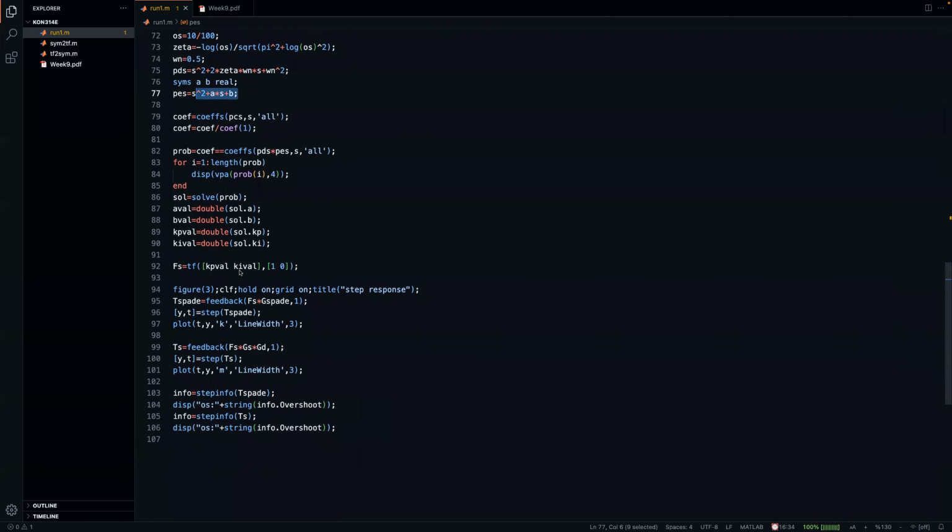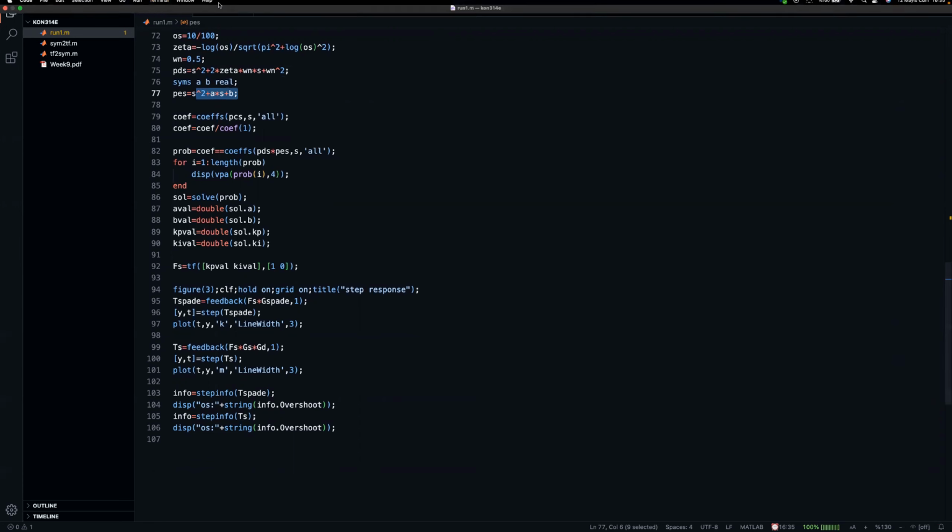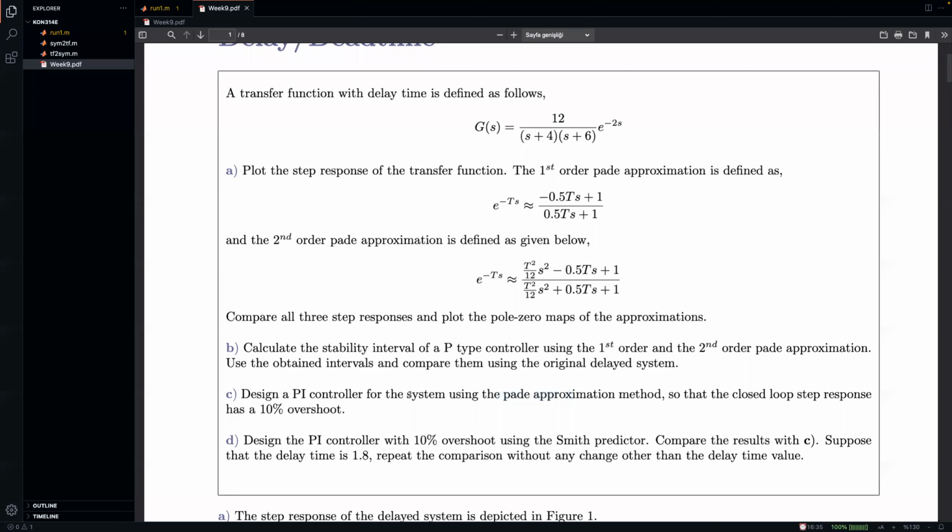And then you have to, of course, again, use tabulation and come up with the best solution that you can and design that. But I'm going to skip that part because I am going to introduce you to these concepts. And my aim here is to give you a basic understanding. And from that on, you can just try your best or design it yourself. So up to this point, we've seen that there's something called the Padé approximation, which takes out the nonlinear term, plugs in the Padé approximation, and from that point, you can use all the tools that you have obtained up to this point, and you can work with that.